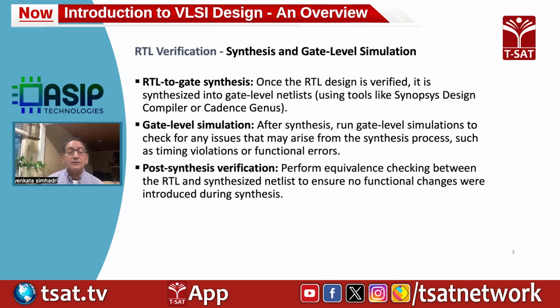And as I said, the RTL design process includes writing RTL code and synthesizing that into a gate level netlist. We will talk about synthesis in more detail later. And once you convert the RTL into a gate level netlist, you have to do a gate level simulation again using the same test bench to make sure that the functionality is still intact and it is meeting the original spec.